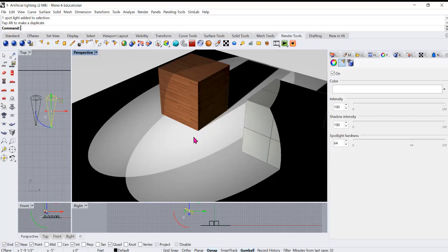Because again, the more lights we have, the longer it will take, and it's even worse when all the light sources are generating shadows. So again, keep it to the minimum. If your computer can afford more than 2 lights without wasting a lot of time, then that's fine. You can use more than 2. But my personal recommendation is 1 or 2 artificial lights. That would include your environmental lights, either your skylight or your sun.